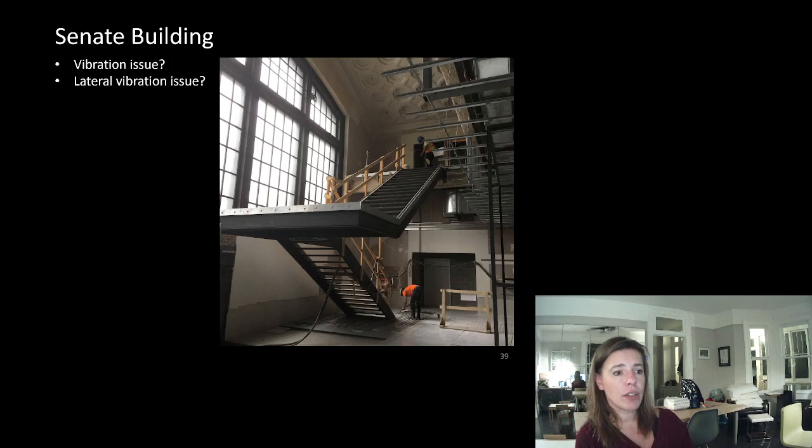The contractor on site said it was moving like an inch. So I said, all right, movement is relative. People, once they're aware of it, think it's something very large. So I said, come out to this corner, tie a platform off onto it, and put sandbags on it. So a sandbag is 66 pounds, so 225 divided by 66, it's 3.4 sandbags.